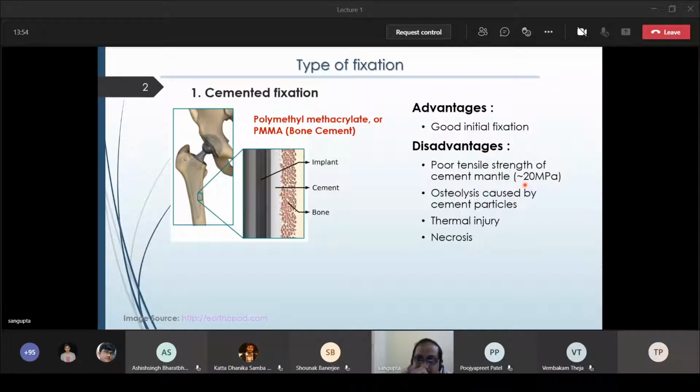Now, the moment it cracks, it can disintegrate the interfaces it shares with bone and implant. There also, if you apply Hoffman's failure criteria, you may notice that there would be debonding at these interfaces as well, due to the low value of tensile strength.